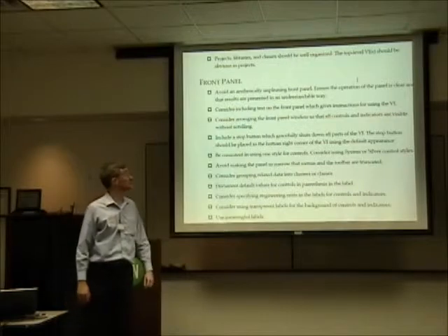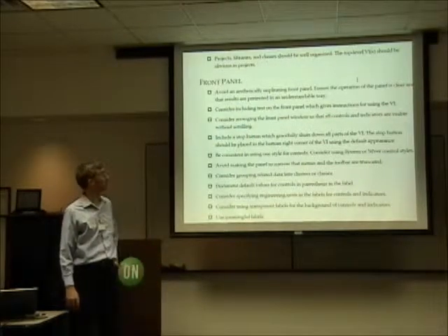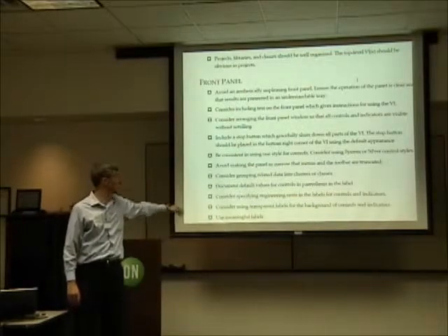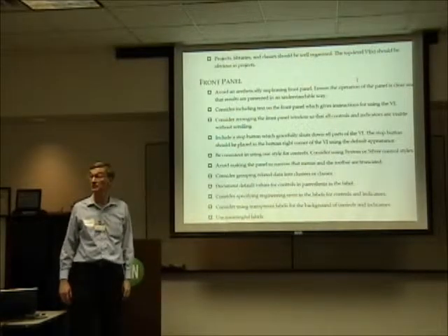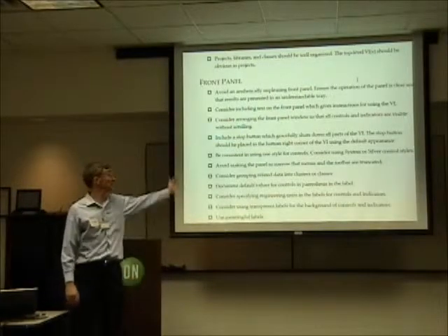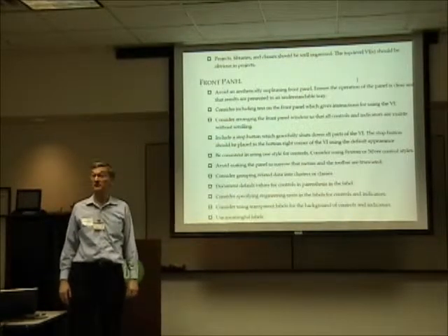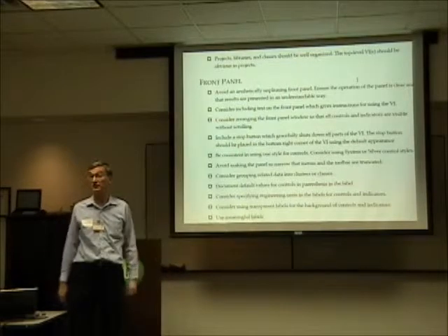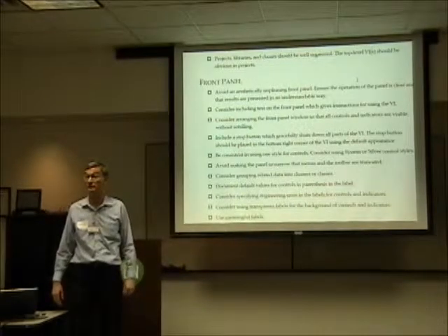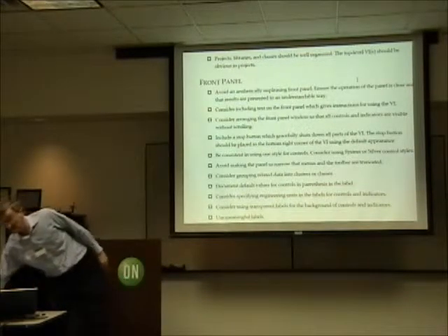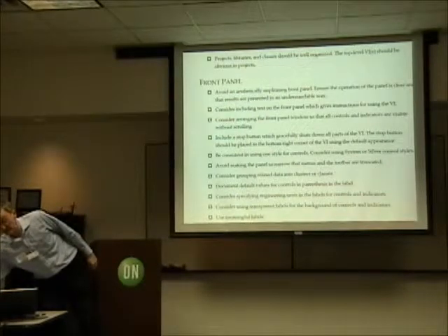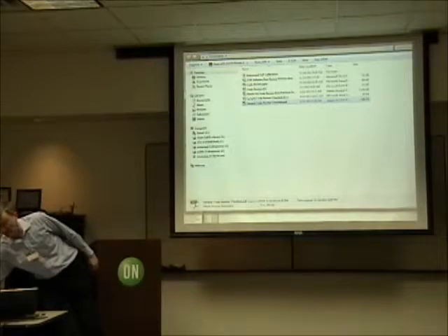Front panel: avoid an unpleasant front panel, make sure it's clear, present in an understandable way, groupings, transparent labels, all of that. Yeah, we go through and try to do that on an individual basis. A lot of this stuff is things that you can't find in VI Analyzer. It doesn't test for it, so it requires another developer or a human being to check for it. I'd encourage everybody, if you're working in a team, to make up your own style guideline. We're slowly customizing this one. We haven't gotten very far.